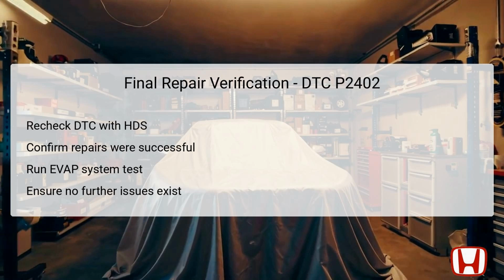Subsequently, running a comprehensive EVAP system test is essential to confirm that the repairs hold up under operational conditions. The absence of further DTCs or irregularities during this stage corroborates that the issue has been resolved. Lastly, ensure the vehicle is functioning smoothly without any active alerts or performance issues to complete the repair process competently.